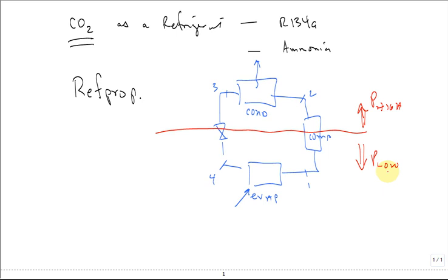And if, let's say, you want to make ice with that, right? You probably want the refrigerant to be coming out, let's say, around 0 degrees F, such that there's maybe a delta T in the evaporator of about 15 degrees F, meaning that it can keep something cold at around 15 degrees F, okay? I forget the temperature for a lot of the frozen products, but it's probably 10 degrees F. Ice cream, I think you try to keep it around 10 degrees F.